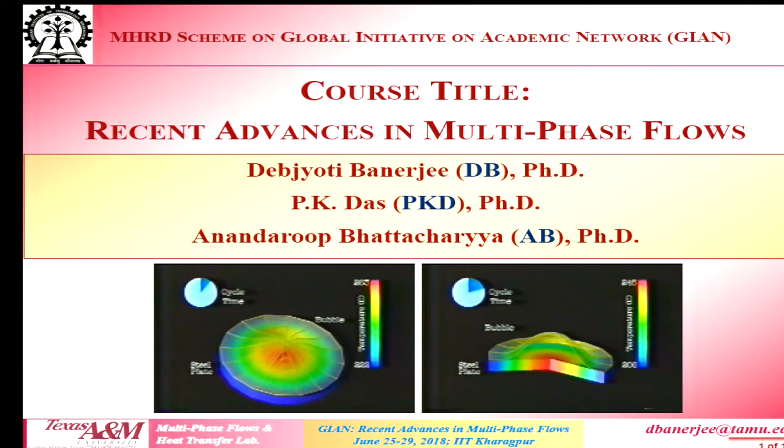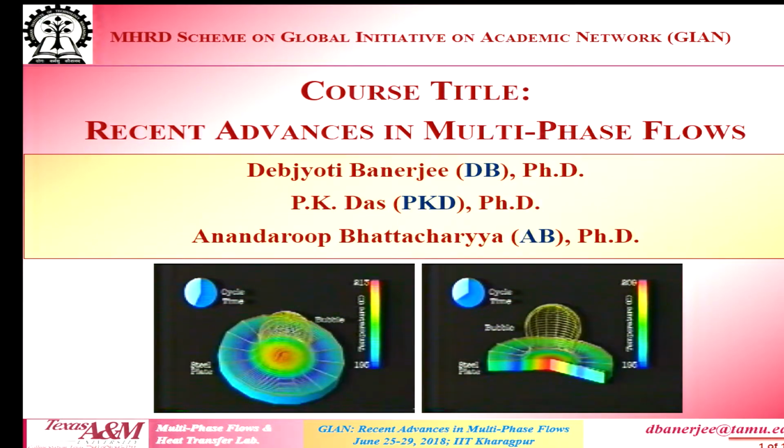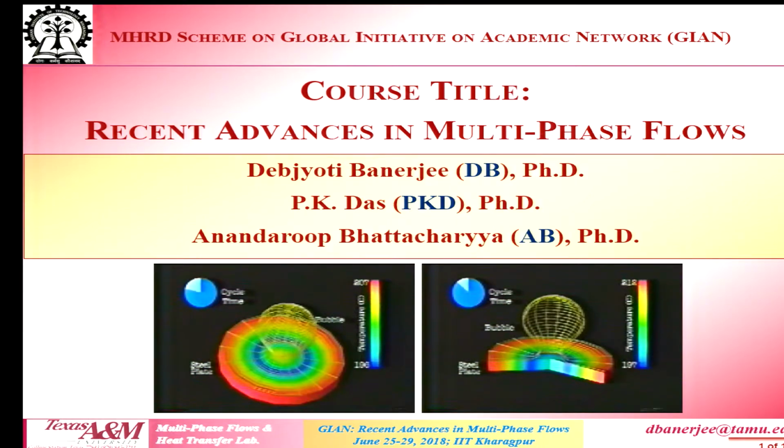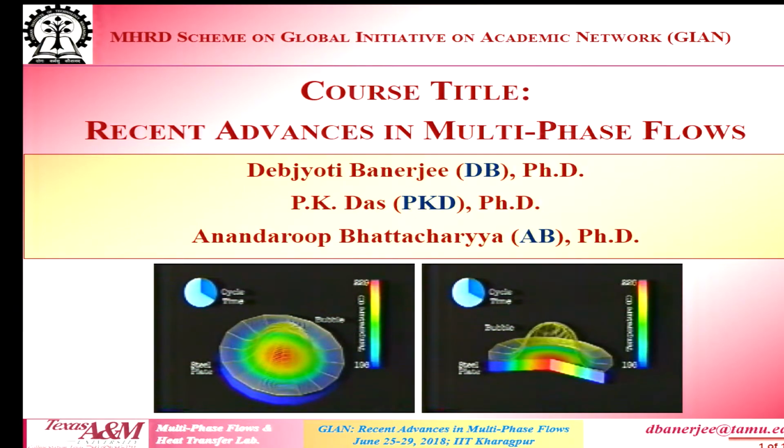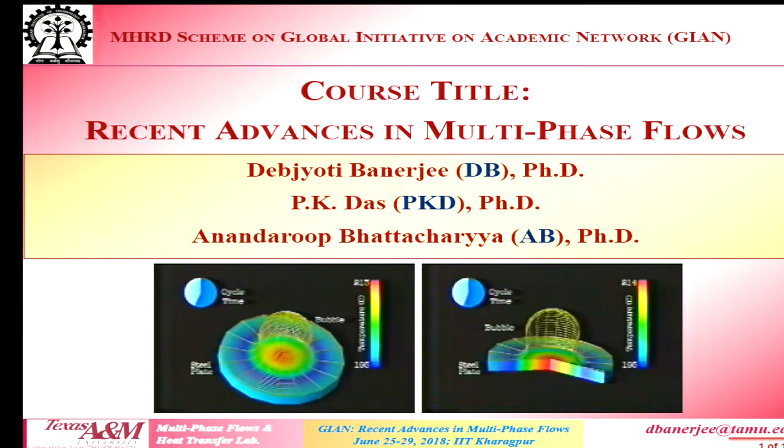So what you see is a CFD simulation. At the point of the minimum vapor film thickness, you get a peak in the heat transfer, and therefore it causes a local cooling. That blue dot is your cold spot, okay. When the bubble departs, your cold spot is in the center, and when the bubble forms initially, your cold spot sort of moves from the outer periphery towards the inner portion of the bubble. So this is how the temperature fluctuates under the bubble.